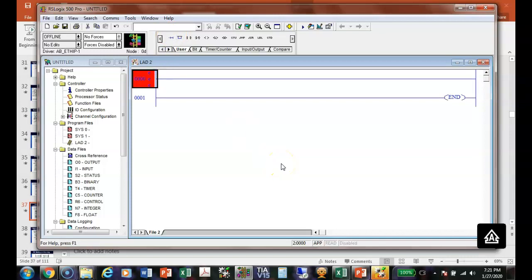It automatically moved the end instruction. So the end instruction is there automatically. You cannot put any device in the end rung. This is automatically in the program. Most of your newer ones don't show that, but that's the actual instruction that causes the program to loop and go back up to the first rung. I'm stuck on this rung.